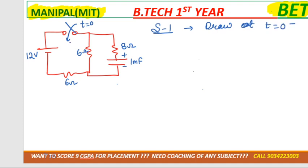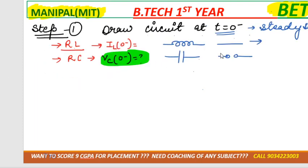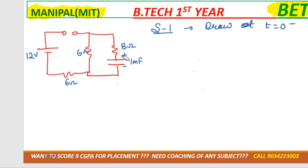Step number 1, we have to draw circuit at t equal to 0 minus. So see, according to the switch, tell me, at t equal to 0, the switch is closed or opened? Tell me. At t equal to 0, see, you have to see it like that. At t equal to 0, it is closed. So just before that, it was opened, right? So it would be opened. And as I told you, in this case, capacitor will behave as an open circuit. So remove capacitor, this will behave as an open circuit. Correct?